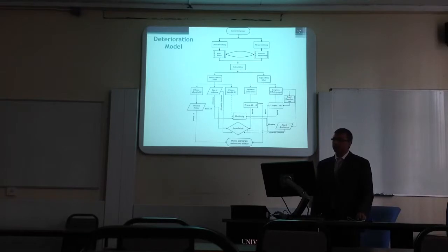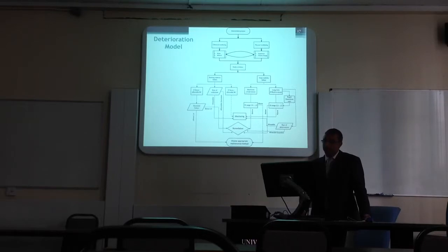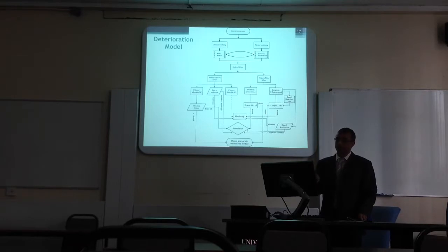Bearing capacity failure is very seldom seen, because when you do a site investigation or the ground investigation, you need to first check whether the ground is suitable to build an embankment or not. And if it is not suitable, then of course you need a remediation for that. For example, if the stress is less than the allowable bearing capacity for the embankment, then in the future you can do monitoring. But if the stress is exceeding the bearing capacity, then you need to know how the stress exceeded the allowable bearing capacity.